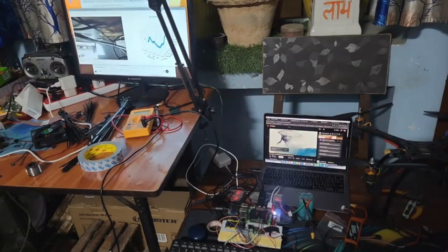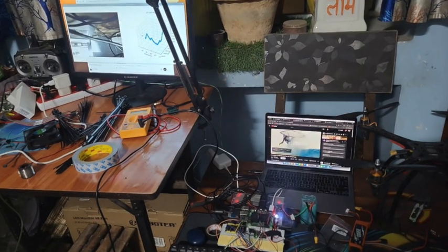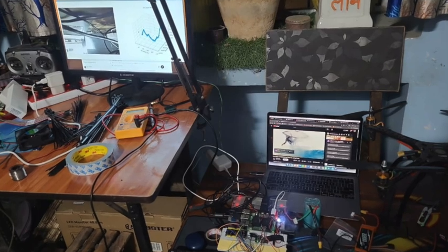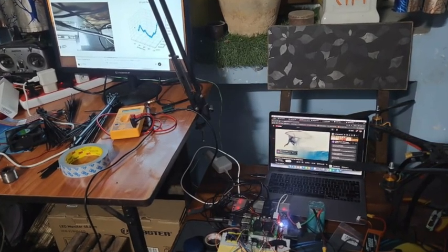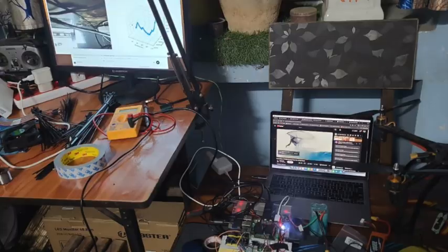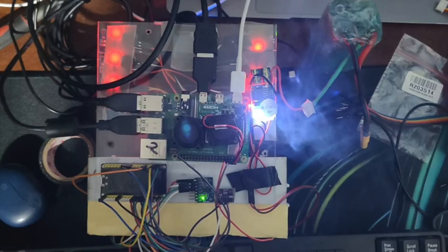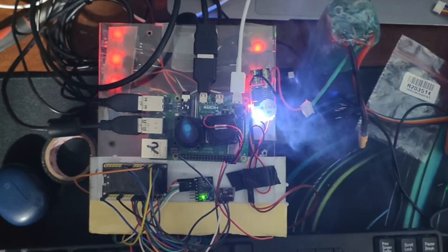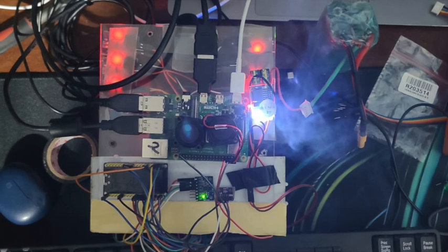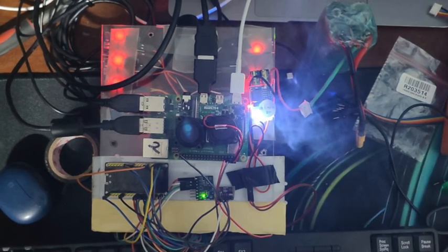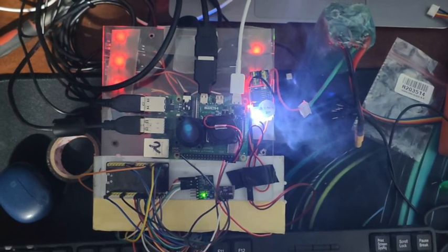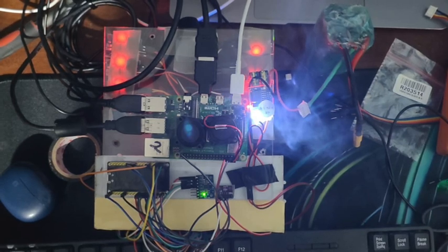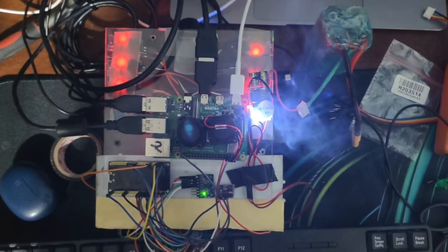This drone carries a complete sensing payload. It includes 6 different MQ series sensors that detect LPG, methane, alcohol vapors, carbon monoxide, hydrogen, and ammonia based compounds. I also use a PM2.5 Sharp dust sensor for particulate measurements, a DHT11 for temperature and humidity, a BMP280 for air pressure and altitude, and an MPU6050 inertial measurement unit for orientation and motion tracking.